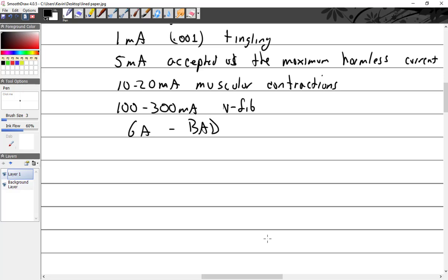So, okay, the point being you can't do that because that's a dead short, and the fuse inside the meter is trying to protect the meter from that. So don't do that. Let's see here.